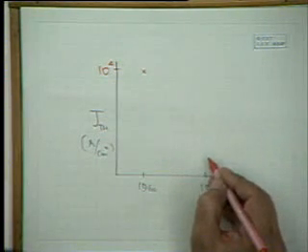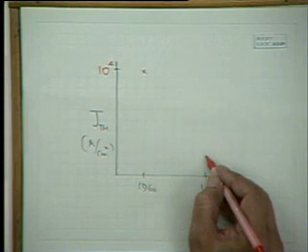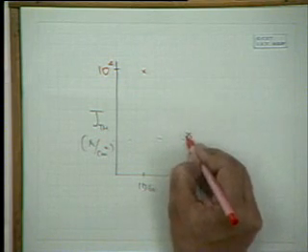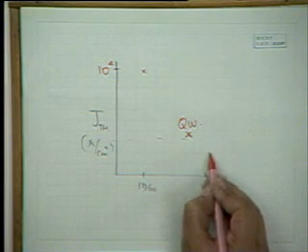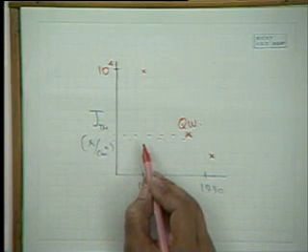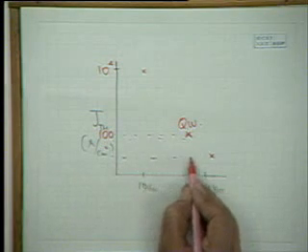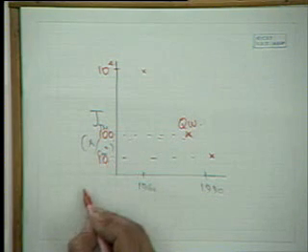And now we are down to quantum wells having threshold currents of the order of, quantum wells somewhere here. And quantum wires and quantum dots have come down even further. This is typically of the order of, say, 100 amps per centimeter squared, and here we've got down to about 10 amps per centimeter squared.